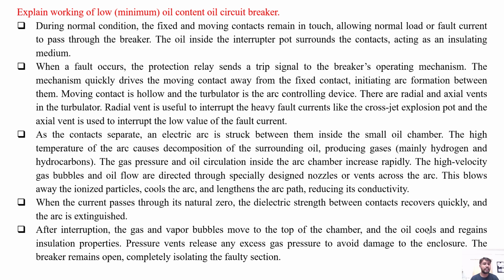The high velocity gas bubbles and oil flow are directed rapidly through specialized design nozzles or vents across the arc. This blows away the ionized particles, cools the arc and lengthens the arc path, deionizing the arc and reducing its conductivity.